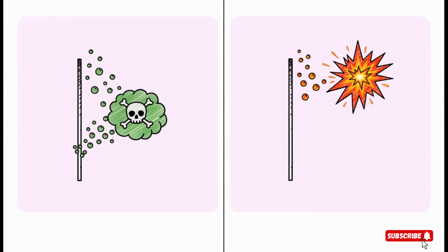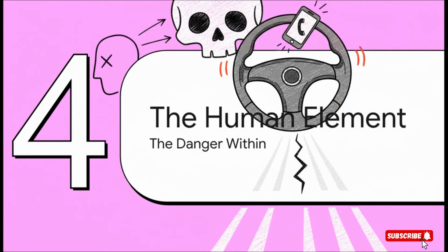Okay, let's break this down because it's really crucial. Our CP systems generate gases as byproducts. Over at the anode, you can get oxygen, sure, but you can also get toxic chlorine or carbon dioxide that can suffocate you, especially in deep ground beds. Meanwhile, at the cathode, you're getting hydrogen gas, and hydrogen is extremely flammable and highly explosive in an enclosed space. This is exactly why proper ventilation isn't optional. It's absolutely essential.